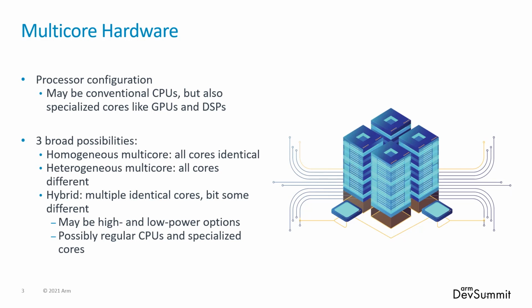And so, just in general, multi-core could be that heterogeneous type where you have a mix of different things. I'll just call that heterogeneous multi-core from now on, where all the different core groups are different. You could still also have a homogeneous multi-core where all the cores are identical. In some cases, that's a group of cores on a single SoC. For example, these application cores, you could have a group of them that are all homogeneous, so maybe you have a quad Cortex-A53.